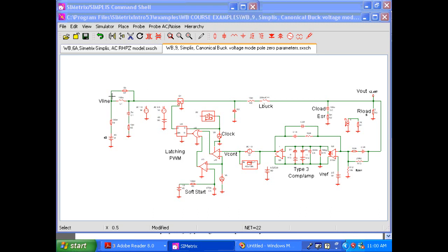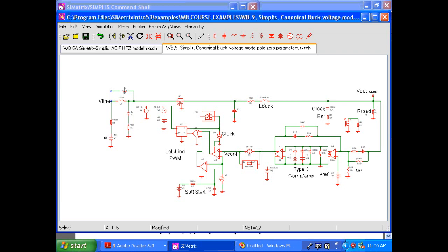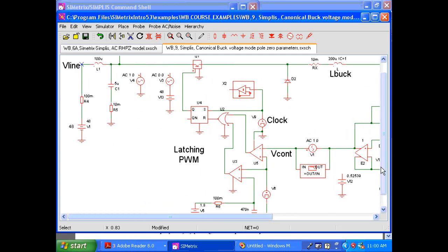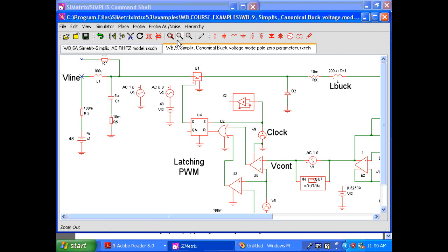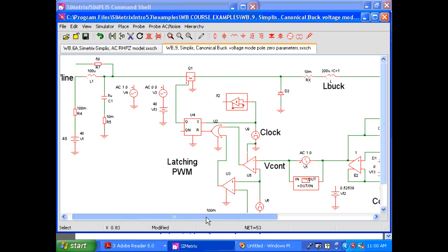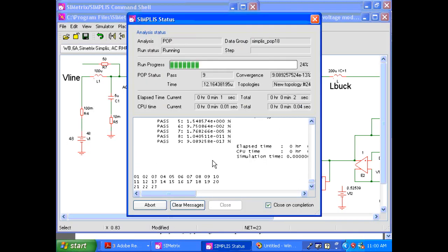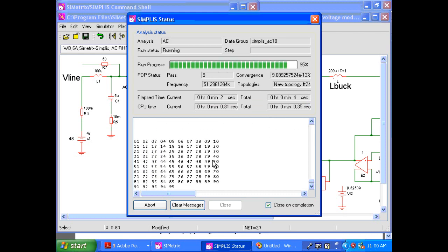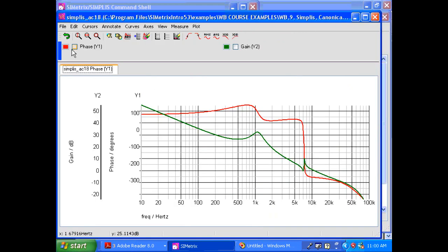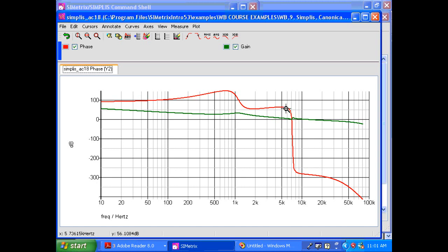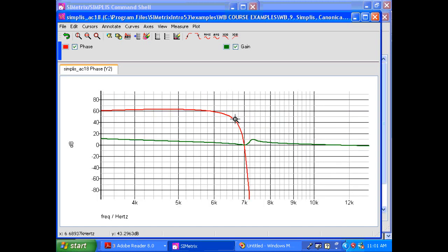Now we're going to take that damping resistor out of the picture. That's 50 ohms. Now to see the overall picture, perhaps I can expand it and show you a little bit more here. A little hard to see, but it's 50 ohms. There you go. Now we've taken the damping away, and we're going to run the same plot again, which is phase and gain of the loop. Now, if you take a good look at it, you'll see we have a problem here. The gain is 1, the phase is also at 0. It's always necessary for the gain to be at 1 when the phase crosses, for it to be a problem of oscillation, of course. But it's happening, as you can see, right there.